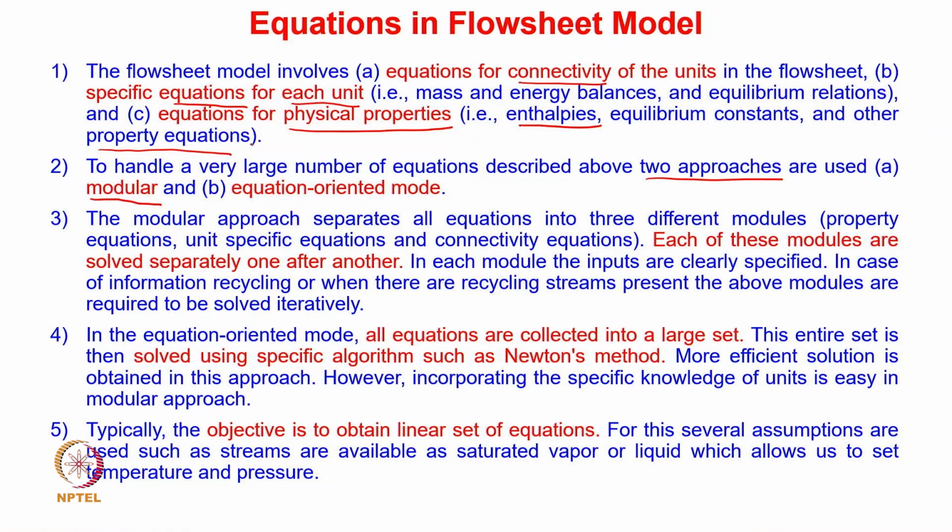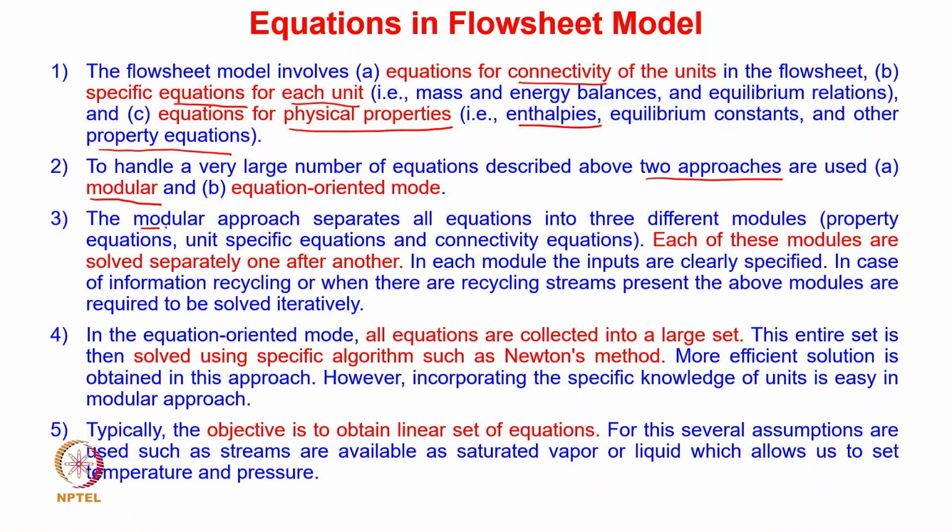In this particular case, first we make a module of physical property equations, then the second module is the equations corresponding to specific units, and the third type of module is the equations with respect to the connectivity of the units. We solve each of these modules one by one. First we solve the property equations, then the equations for each unit, and finally the equations for connecting different units. So this is what we do in a modular approach.